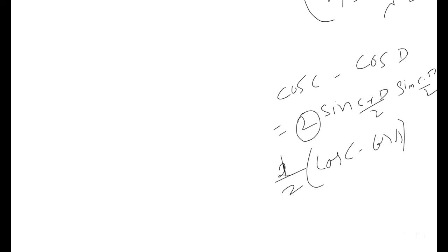In previous, transmitter, receiver, duplexer, this side antenna. What is this one? Antenna. Previous whatever we discussed, our final target is fixed one. What is this one? Final target. Here the final target is moving. So this continuous wave radar is used for moving targets, stationary targets or clusters. It is working on the principle of Doppler effect.